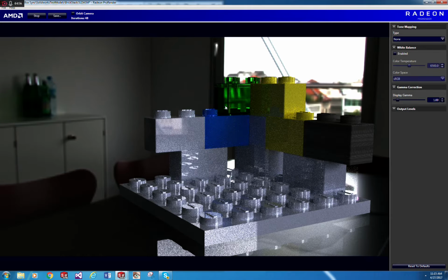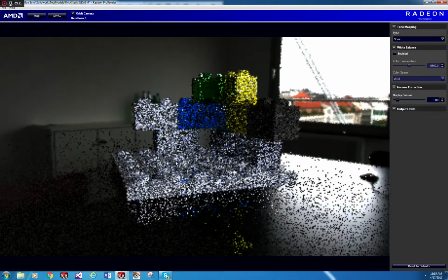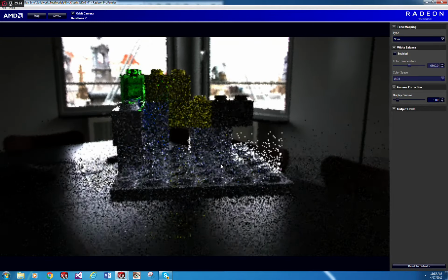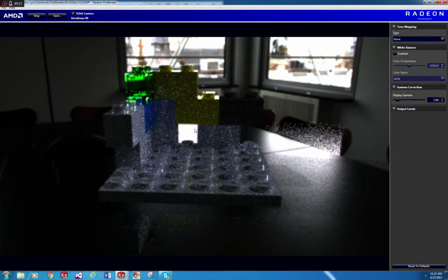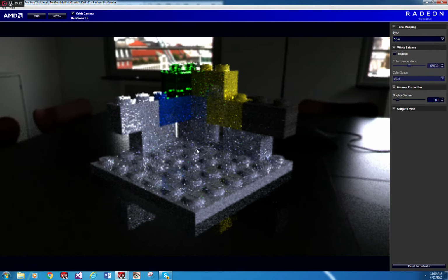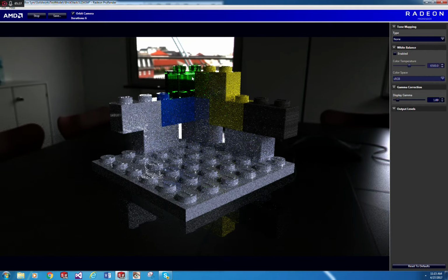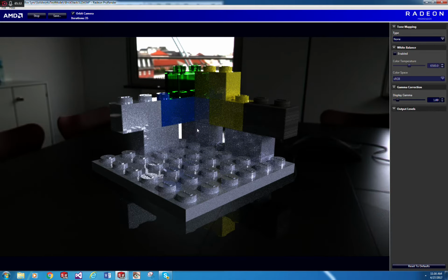And there are a couple of things you can do to affect the quality and the way that your output looks. The first thing, a very useful tool, is there is a ProRender specific camera. I can go ahead and click Orbit Camera, and now by using the middle mouse button I can rotate and adjust my view using the ProRender preview quality, and you'll see that the quality drops a little bit so that you get faster interaction, and then as soon as I let go of the mouse it comes back into sharp focus again.